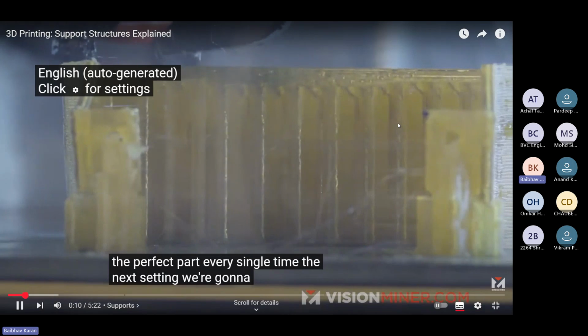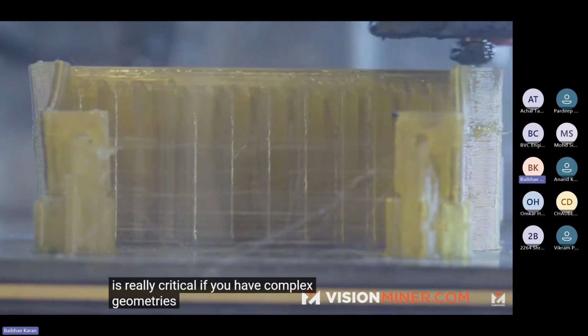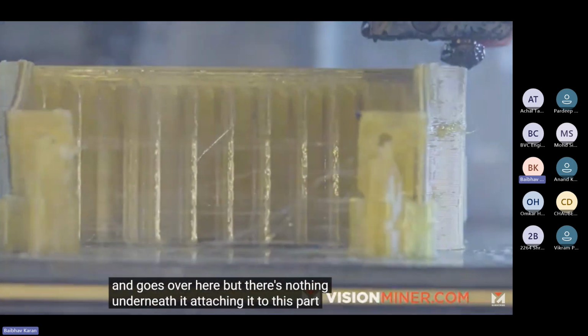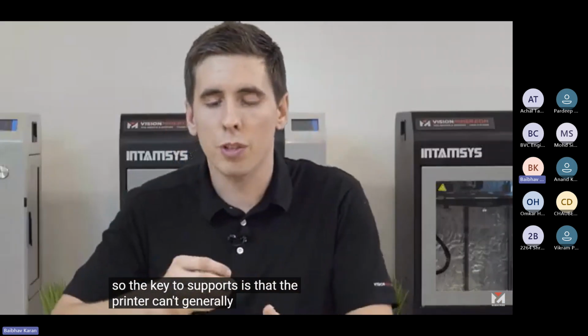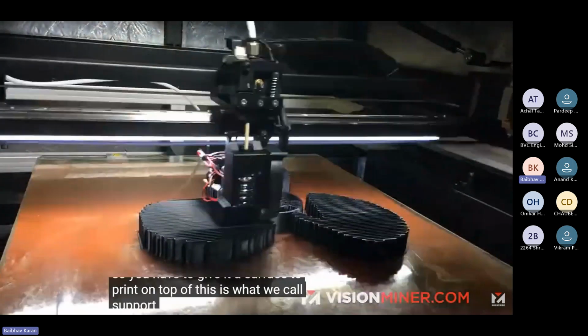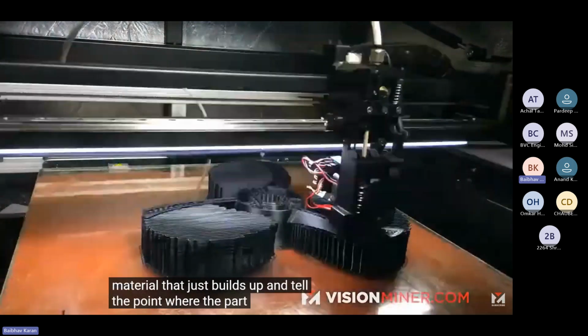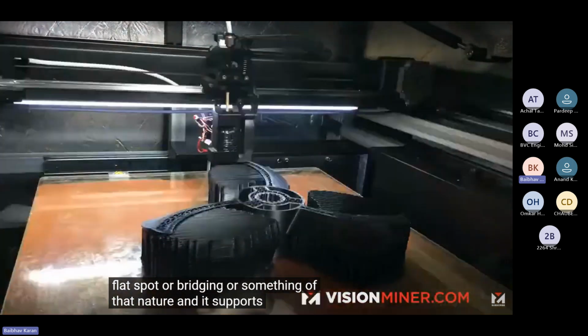Hey guys, today we're going over tuning basics and how to tune your print to get the perfect part every single time. The next setting we're going to go over is supports and support settings. Now this is really critical if you have complex geometries where a part comes up and goes over here, but there's nothing underneath it attaching it to this part. So the key to supports is that the printer can't generally print in mid-air, so you have to give it a surface to print on top of. This is what we call supports, where basically it's sacrificial material that just builds up until the point where the part begins, that flat spot or bridging or something of that nature, and it supports that material.